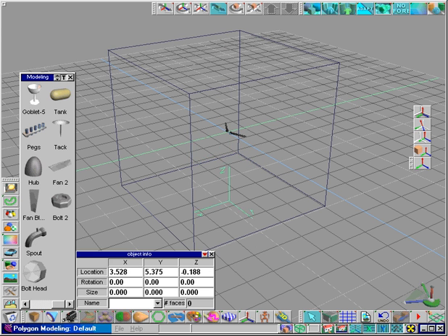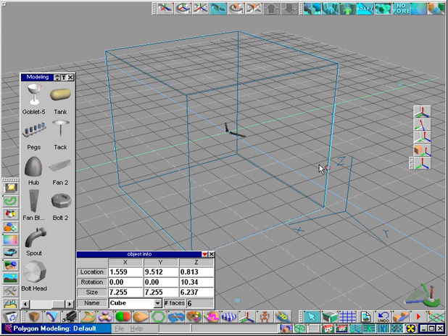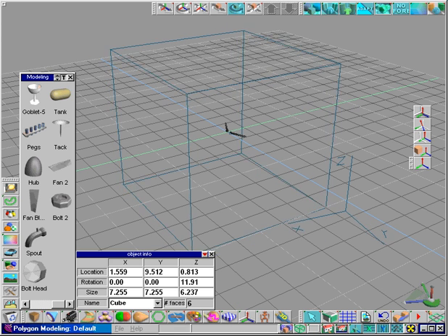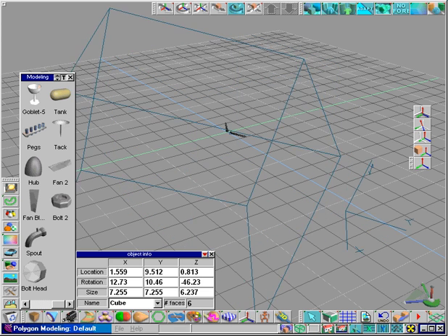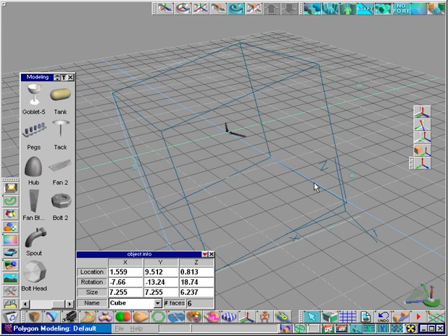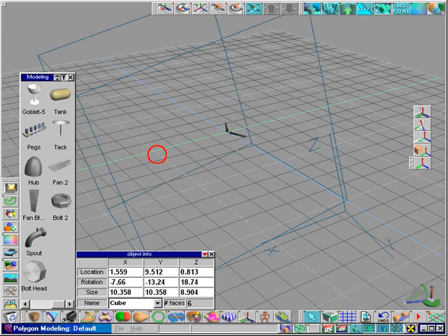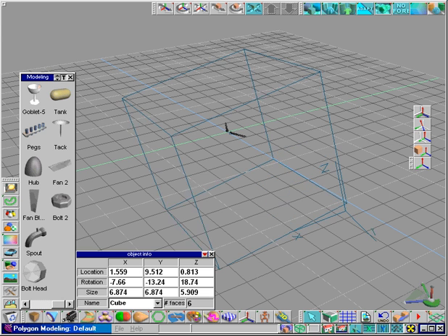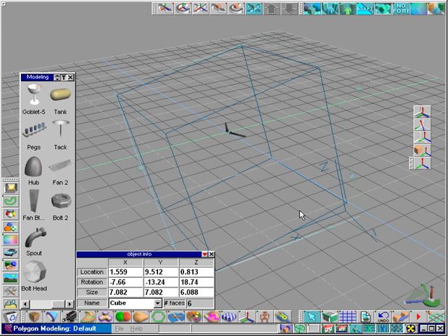By clicking on the object, the axis becomes inactive but remains visible. Clicking on the axis tool will activate it again, which is the 3rd function. When the axis is inactive or hidden, any translation, rotation, and scaling performed affects the object according to the axis position. The following exercise will demonstrate the use of the axis tool to create a piece of geometry.